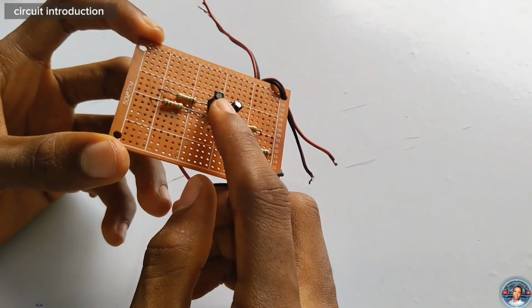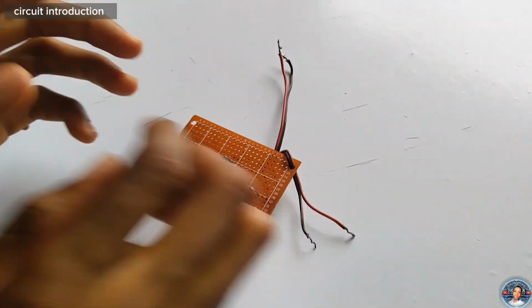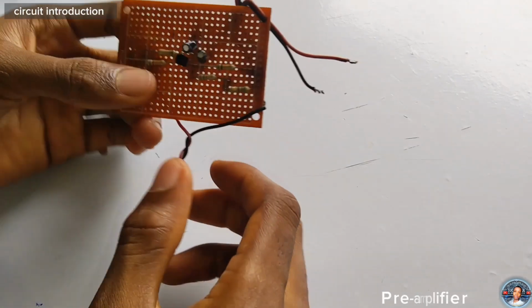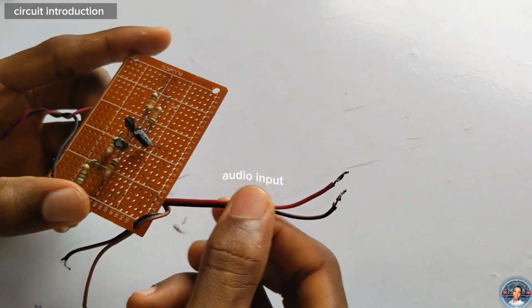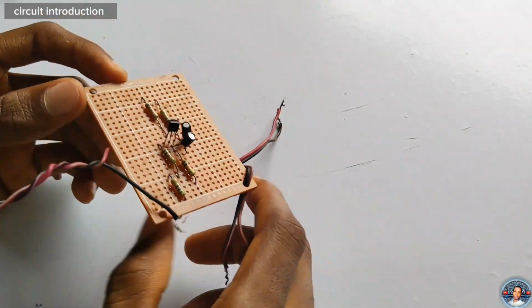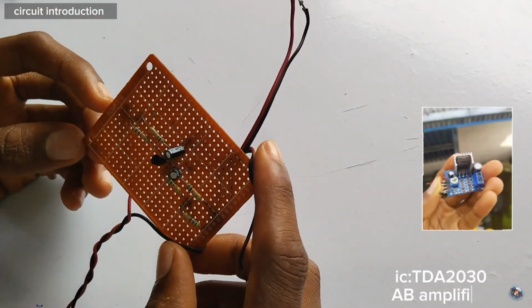Okay, now you can see the transistor right here. The transistor is used as an amplifier. A little tip: the transistor cannot be directly connected to the speaker, so using a transistor as an amplifier is really using it as a preamplifier. You can see the positive, this is the power supply line, this wire is the input of the transistor, and this wire is the output of the transistor. This transistor is going to be connected to the TDA2030 module.